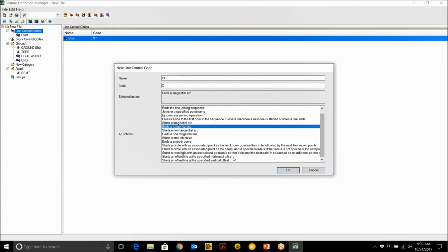What I would say is that I think it is probably possible. My only concern would be, if you're shooting the gutter, you have probably a 6 or 8-inch reveal of the gutter to do a vertical offset and then moving it back. Because remember, when you take a shot, it's a 3-dimensional shot, both horizontally and vertically. I could see a benefit maybe with top of curb, back of curb, and then a sidewalk if they're roughly the same elevation. But for that one shot, you would hold that vertically, so you'd have to also do a vertical offset. But you might be a little bit lower. So that might be something to think about. But yes, Chris, if you could do that, that would be fantastic. James, if we didn't completely answer your question, please feel free to type in and we'll continue the conversation. That's a great question.